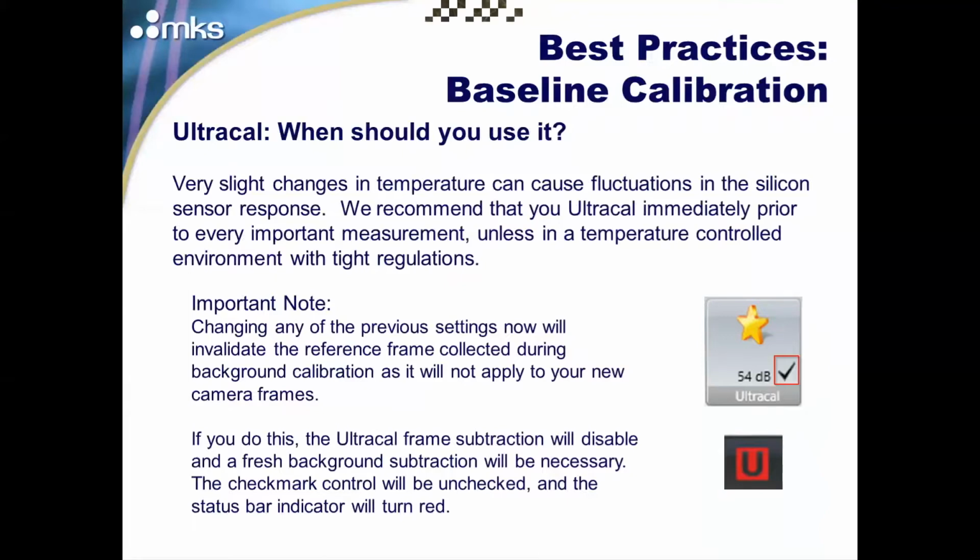And we realized there was an oscillating fan running in the room, and every time it blew in our direction, the response of the camera would change. So it really is that sensitive, and in really high precision beam profiling, even somebody walking past the camera can cause a measurable fluctuation.